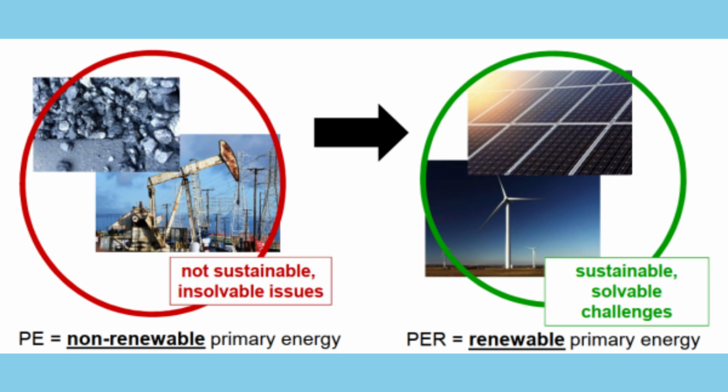That's why PER introduces factors. A PER factor shows how much renewable energy is required to meet a building's final energy demand. For example, a PER factor of 1.5 means you need 50% more renewable energy to cover the same demand because of storage or distribution losses. The higher the PER factor, the more valuable efficiency becomes.